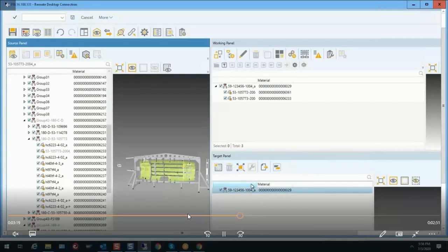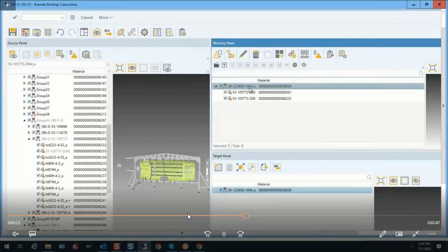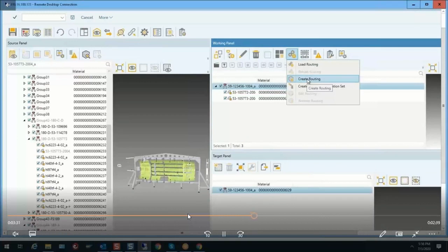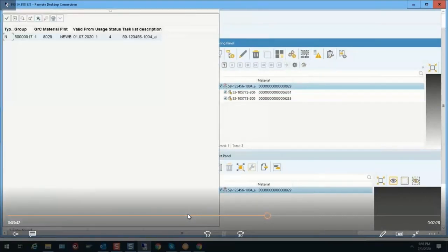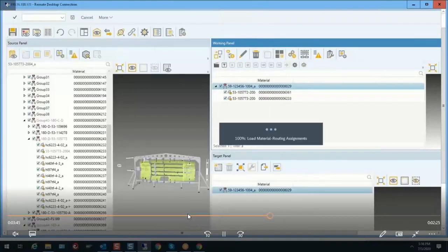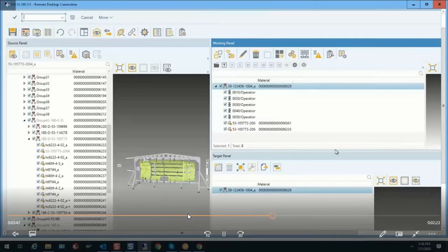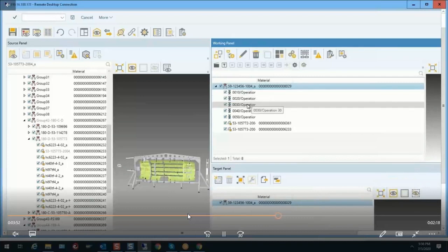Now, the other really cool byproduct: not only does it create a new bill of materials for you, in this case the manufacturing bill of materials, and not only does it create a routing for you, it also gives us what's called a visual work instruction seed file. And the visual work instruction seed file is what we're going to start with in another tool called Visual Enterprise Author to extend even farther and make our assembly and disassembly operations, basically making our 3D animated work instructions.